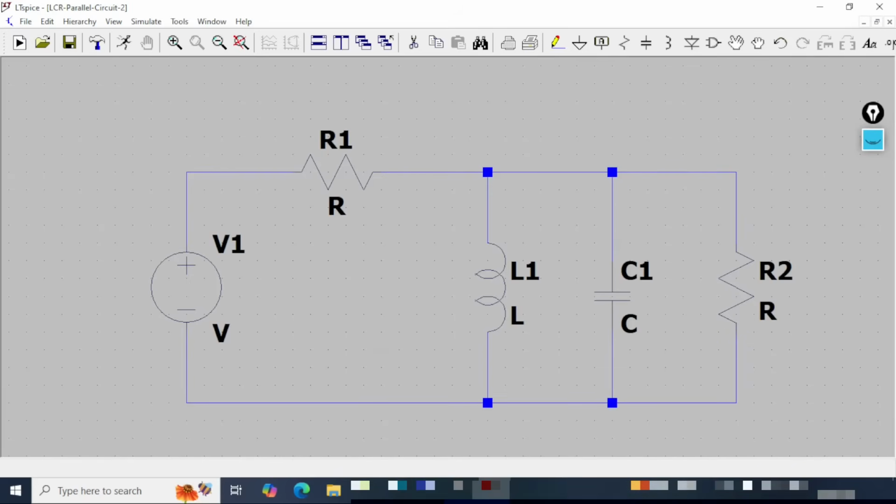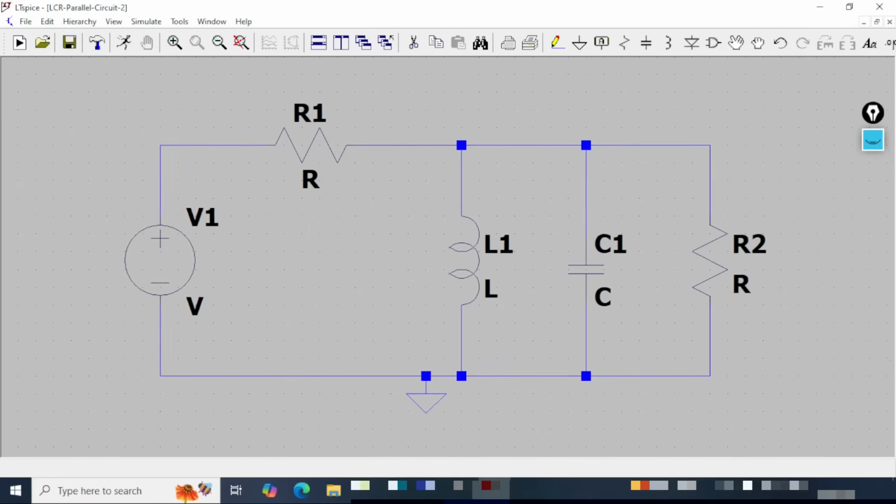I'll right click to vanish the wiring, and I'll save the file. One thing is remaining: the ground line is constructed, however, the physical ground has to be added in the circuit. For that, I'll hit G from the keyboard and I'll click here to place it. I'll right click to vanish it. I'll hit W to wire this ground to the ground line. I'll right click to vanish it. Now I'll go ahead and save the file. You can see all the circuit component placeholders are there.